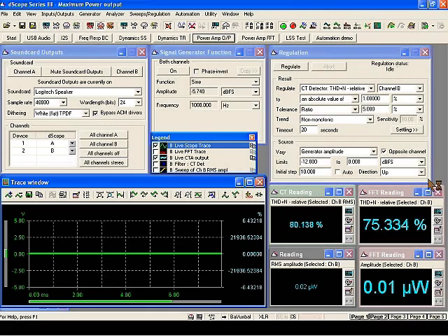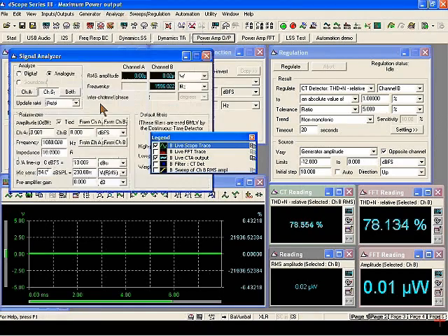So I've got a test set up here that allows me to analyse the total harmonic distortion plus noise and power output of my amplifier all at the same time. Now, in order to measure in units of power, what I need to make sure that I've done is told the test system something about the load impedance that my power amplifier is delivering current into.